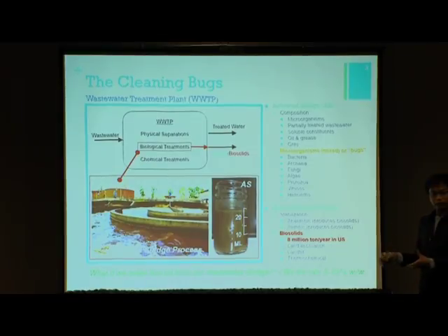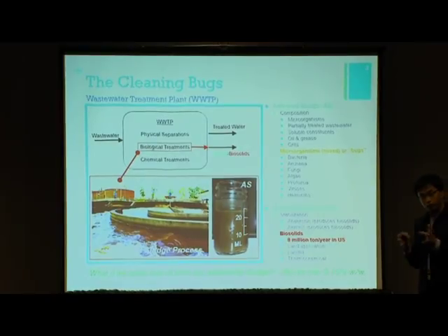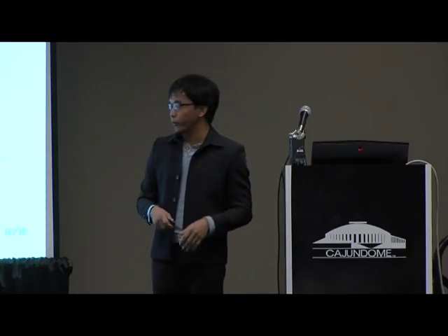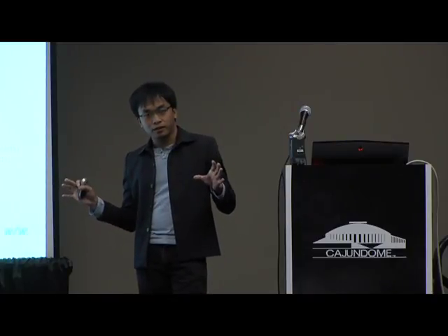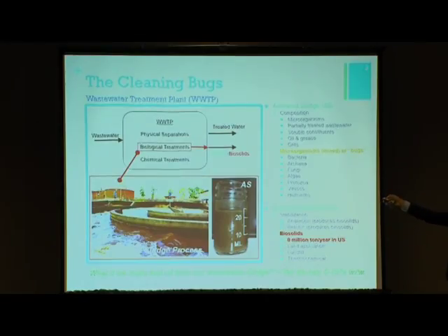Now, the idea here is that these microorganisms assimilate organics from our wastewaters to reduce the BOD, COD, and other organics in their nutrients, in order for the wastewater to be treated water to be disposed in our rivers, bayous, and lakes, and other bodies of water. In the process of treating our wastewaters, these microorganisms grow. And there are these different classifications of microorganisms that are growing. We have bacteria, archaea, fungi, algae, protozoa, and even viruses and helminths, and we call them the bugs. There are also other non-organics in that so-called activated sludge, the consortium of microorganisms.